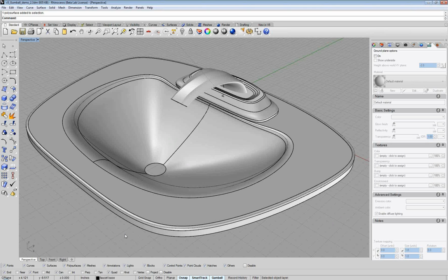Okay, here's one. Let's get to this one from Curtis. It says, when you fillet the faucet base as a surface, what happened to the inside surfaces? Did they update and keep a uniform shell? Is that clear? No, the inside surfaces, those interior surfaces from the shell, did not get changed. So those interior surfaces still have a sharp edge.